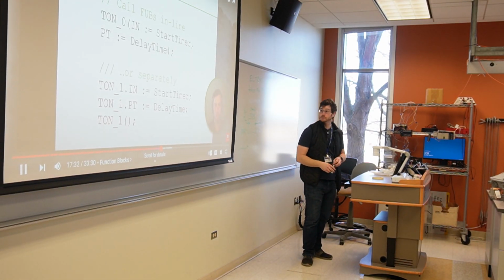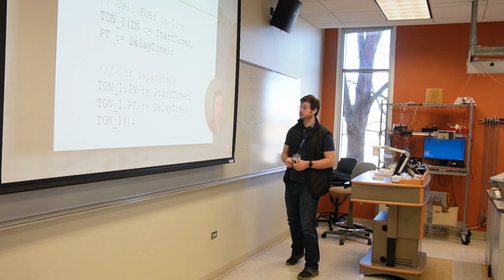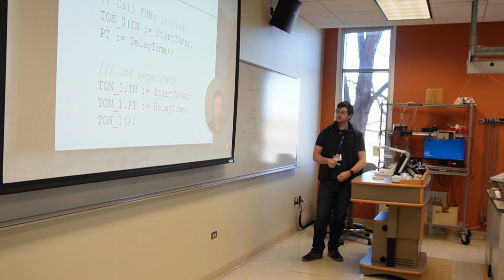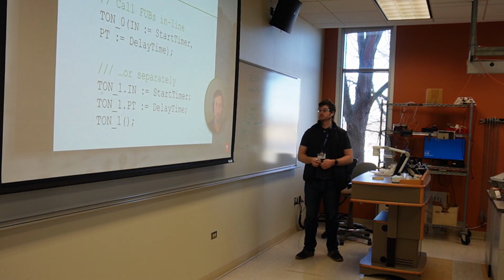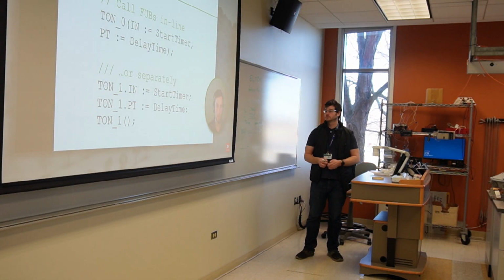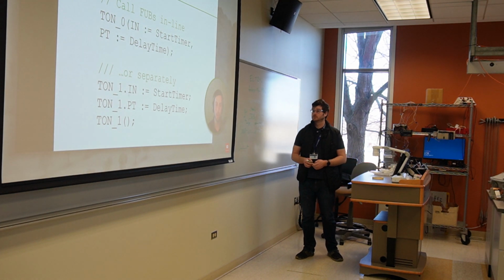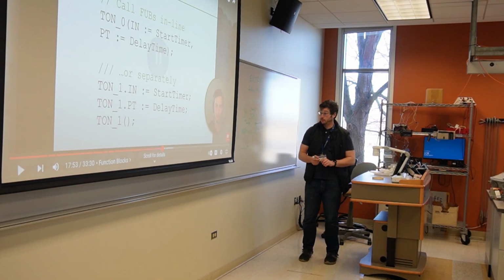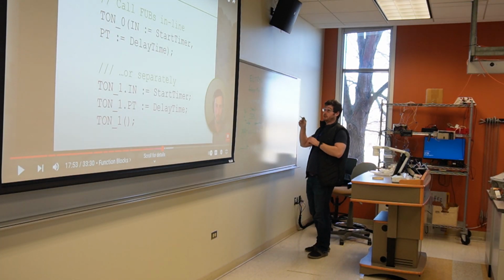It's a little bit coding preference and a little bit usability and readability. So the other way that you can do it is to explicitly call out the inputs using this period notation. You would put the name of the function block, period, the input, and then you assign the value. So this is the other, literally the syntax is different.